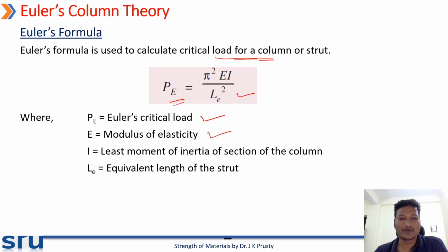E is your modulus of elasticity. I is the least moment of inertia of the section. So we need to carefully find out the least moment of inertia.